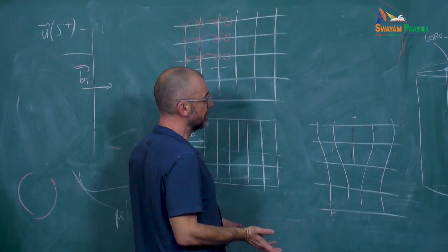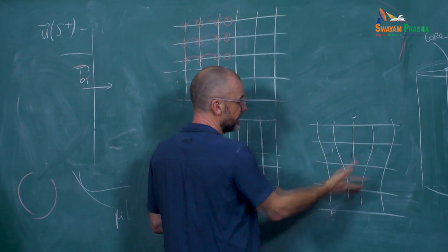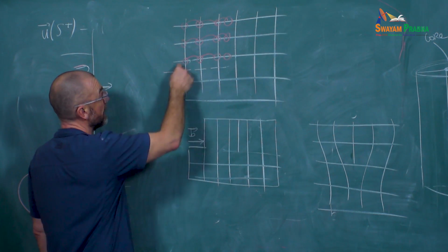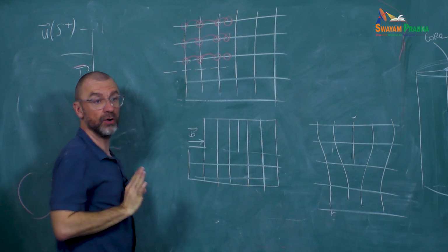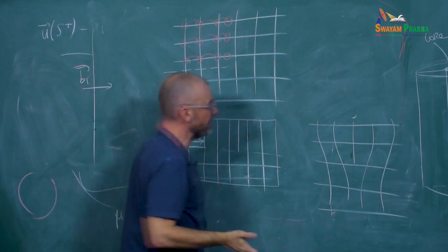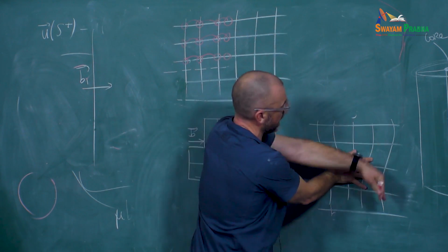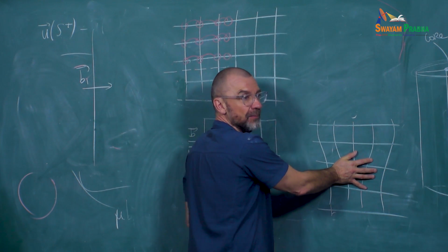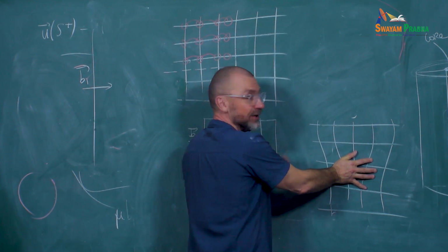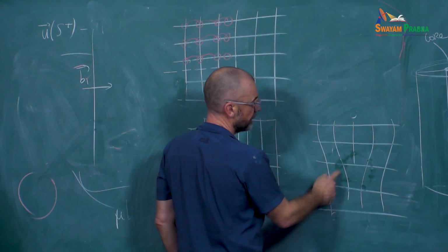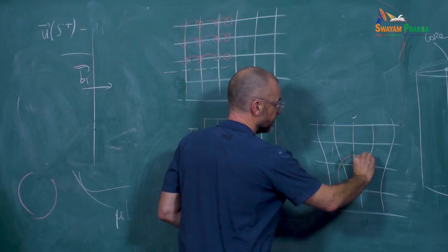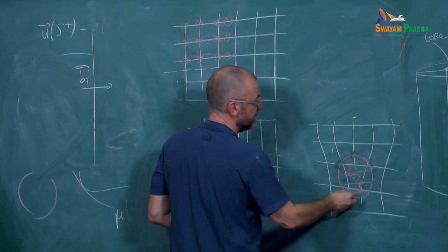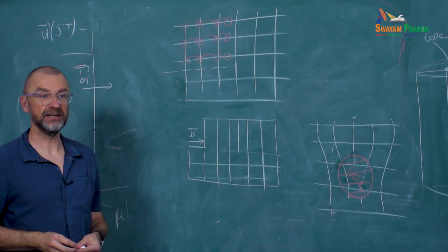And so here, the magic of a dislocation. This dislocation, we call it a perfect dislocation because the Burgers vector is a vector of the lattice. And so when I move the atoms, I do not create any fault along the surface. And the magic with a perfect dislocation is that if I look anywhere except where I've put my hand, I have a perfect crystal except for some elastic deformation. All the big rearrangements occur here. And so this is the core region. This section here is outside of elasticity. All the rest is inside elasticity.